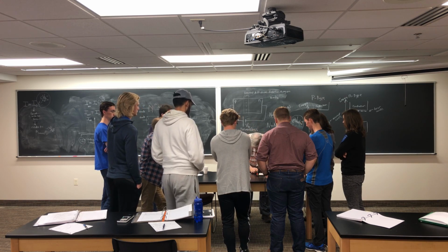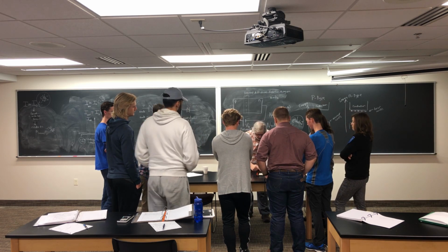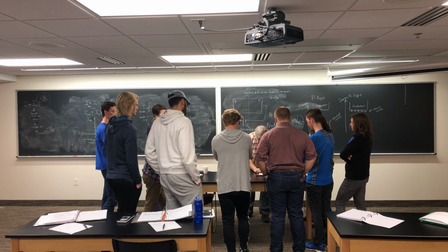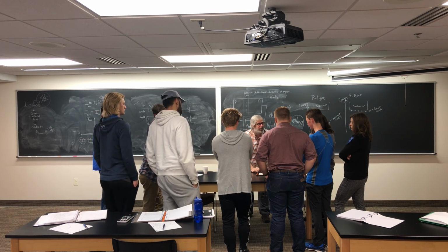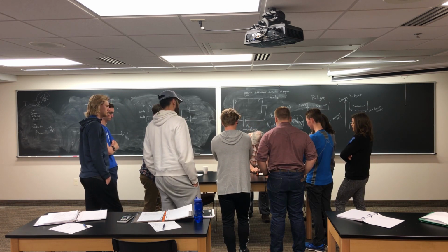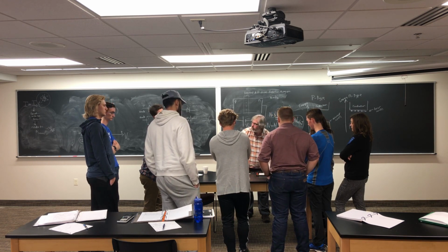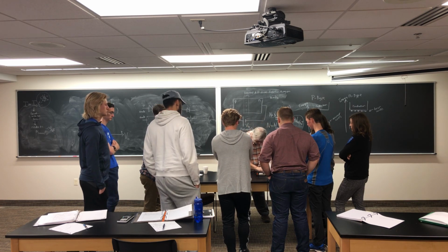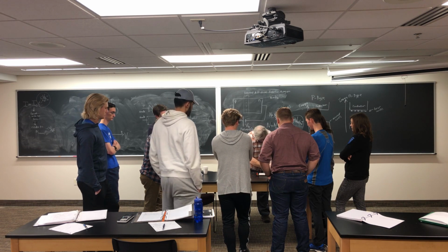of that diode. Okay, so this is called a breadboard. I don't know if you've worked with these before. So see that slot across there? That breaks this, but anything that's on this row is connected. Then there's a break, and anything over on this side is connected. So I attach it to this side of the diode. This side of the diode now I want to go back to the negative side of my battery. So the little thing, I'll just connect there, connect to the negative side.